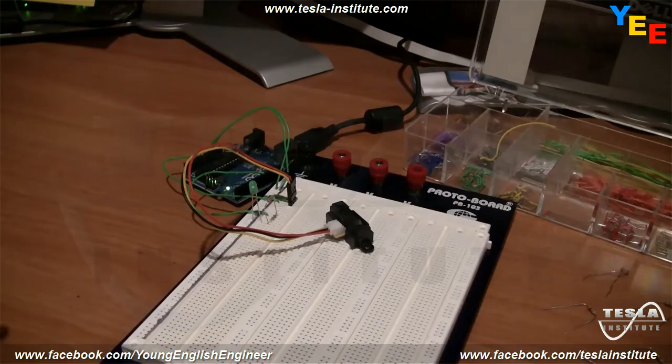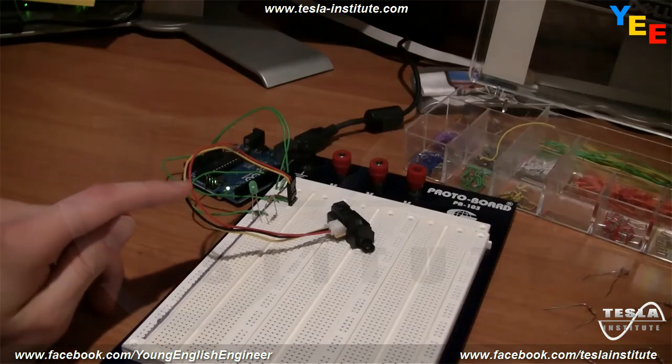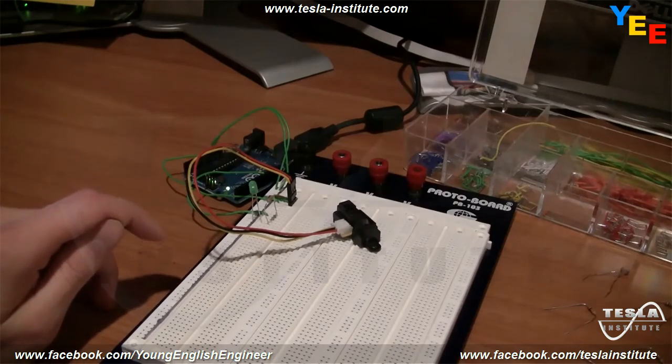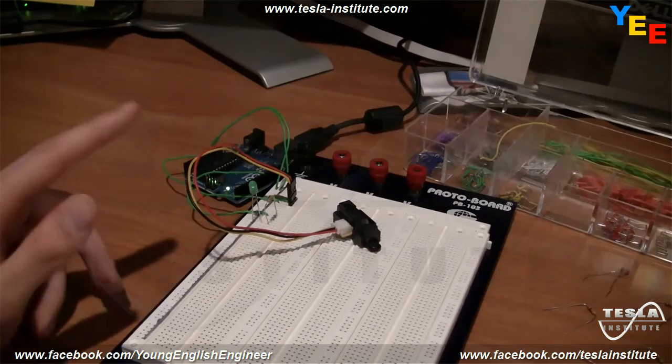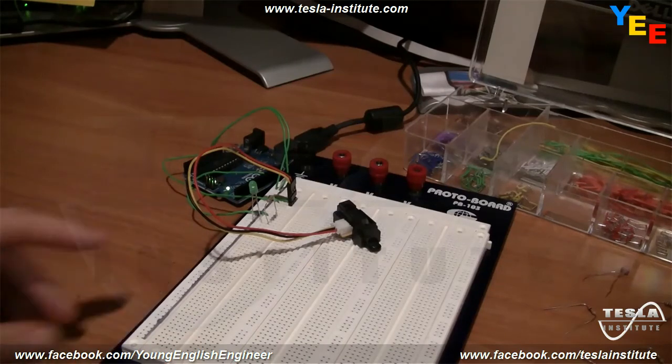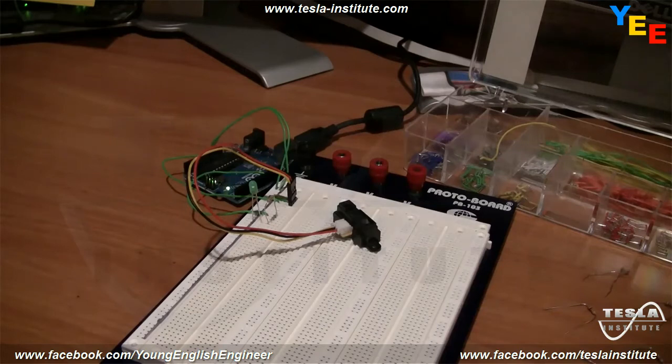All sensors that come like this will usually have 3 wires: a voltage wire, a ground wire, and a sense wire. The red wire, we give it 5 volts. Ground gets connected to ground, of course. And then the yellow wire returns a value between 0 and 5 volts that we can feed into the analog to digital converter in the Arduino and use it to measure a distance value.